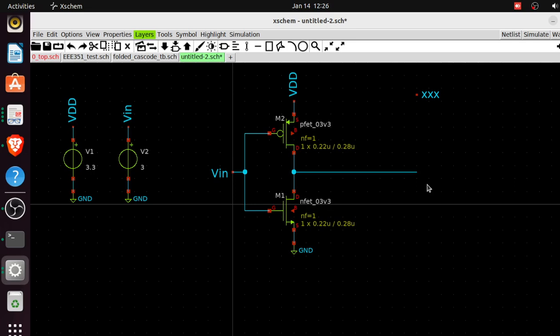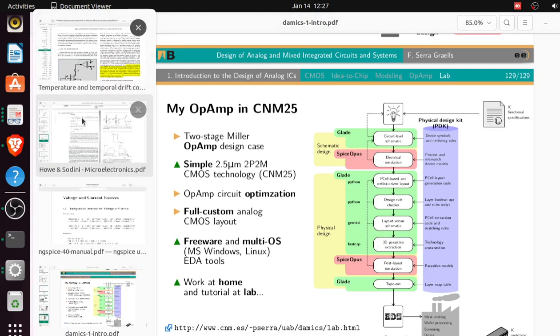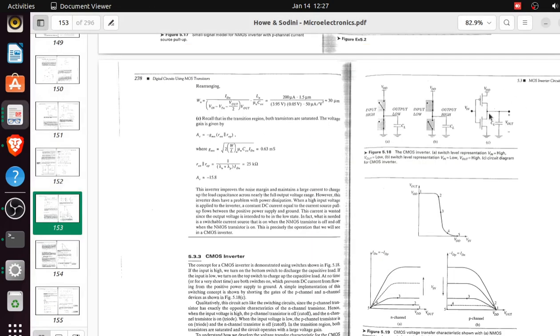And the gate of the MOSFET, which will serve as the input for the NAND gate, is capacitive because there is an oxide capacitor there. So that kind of capacitor we have here, we're just trying to model the working environment of this CMOS inverter. So that's why I want to place it here.